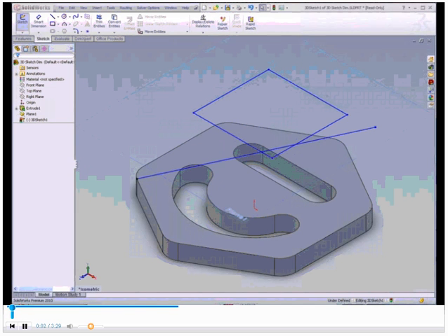Okay, so this project is for the 3D sketch, and this concentrates on improving the way we add dimensions to 3D objects and objects in planes to make things much more consistent with the 2D environment. Specific things we've done is for entities that lie on a plane, we can now dimension to external objects. For entities which lie in 3D space, we can now add angular dimensions. We can also add linear dimensions along a specific axis and along the object itself.